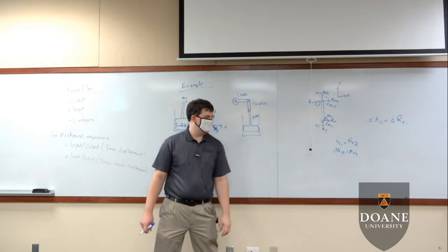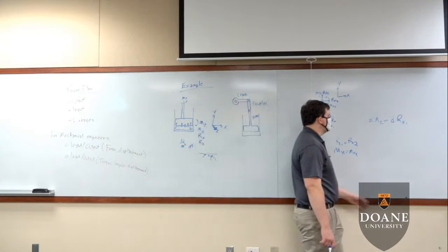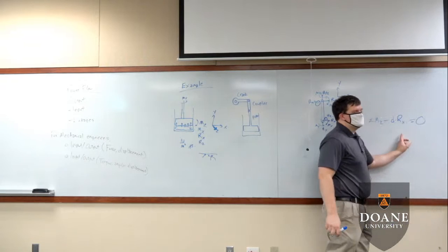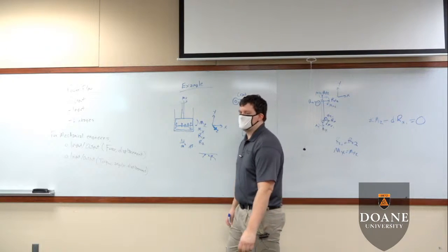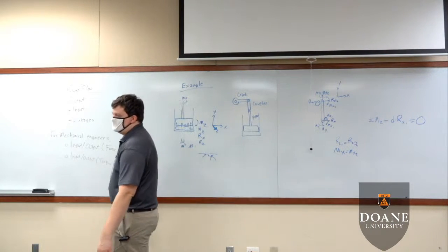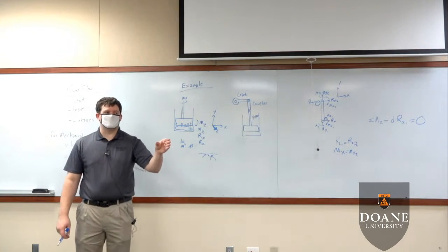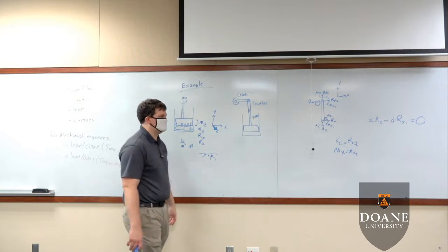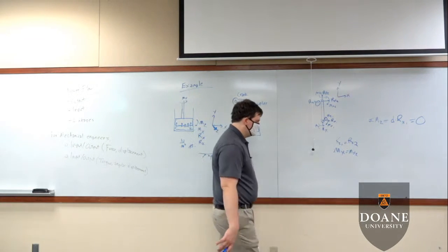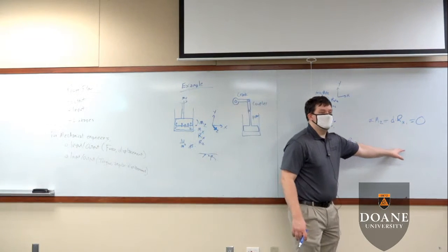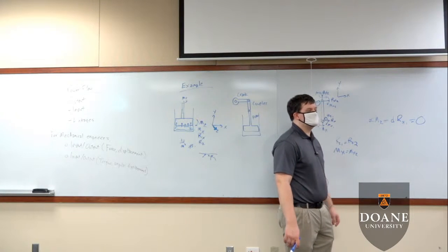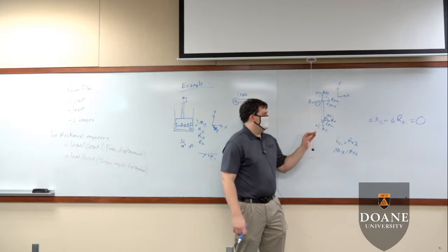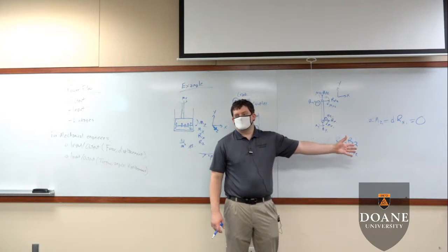So what we're dealing with here is Rx, this is equal to 0 if we don't have any angular accelerations. So if this component is statically moving or is moving at a constant velocity, angular velocity, etc., this is equal to 0. And in fact, in machine design, we're going to assume that the accelerations are small enough that that's pretty much always going to be equal to 0.